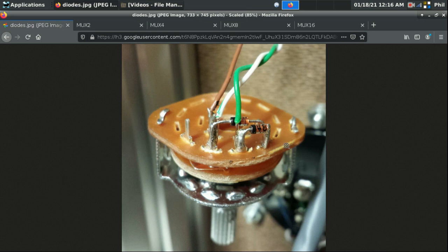If we look at this switch graphic here, we can see that we have 4 positions on the selector switch: position 1, position 2, position 3, and position 4. If we were to wire this switch in a 1-to-1 configuration, we would have to use 4 inputs, input 1, 2, 3, and 4, respective to the positions on the switch. With the multiplexer setup, you basically break down your need for available inputs based on the amount of multiplexing you'll need.